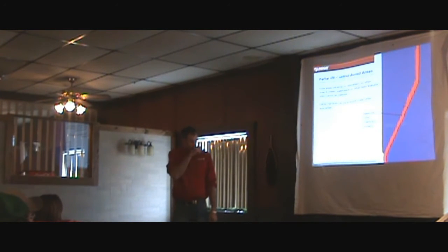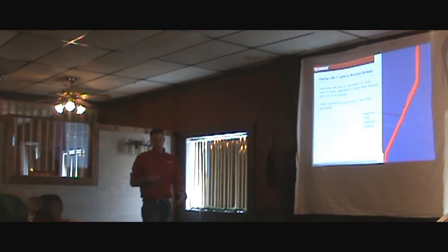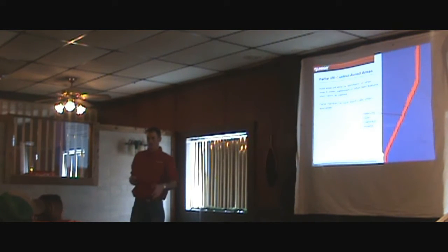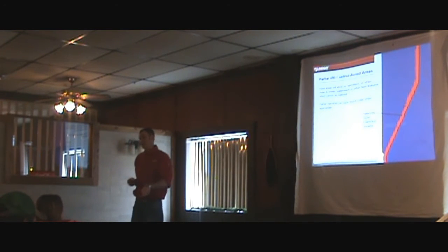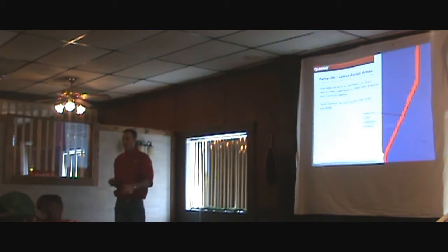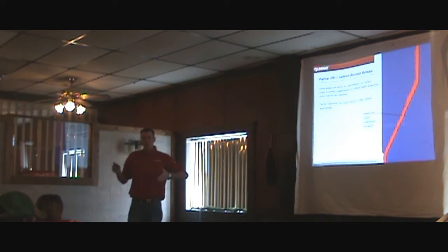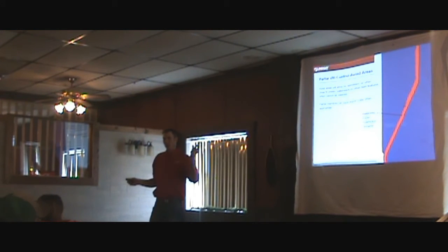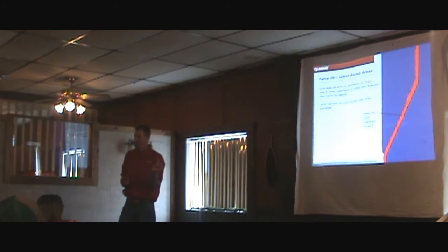Sometimes guys will be pricing this product line, and maybe they want to control 5 or 6 spans of a 7-tower pivot, but they don't want to buy that extra tower at the pivot point. Well, by not buying that 1 tower, A, I've got to add a repeater, which still adds some cost, and B, you cannot run it in full VRI mode. So you can do a partial VRI, but if you're close to having a full VRI, there might be enough opportunity to spend those few dollars to finish it off. If that makes sense.